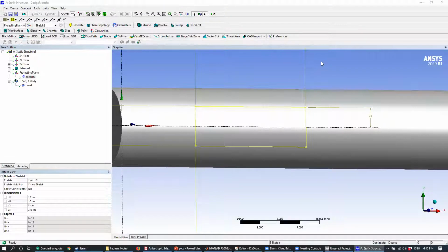You'd still have to sketch it, I think. So one way that I would do it is I would make a plane that's coincident with the feature that you want to project, and then make a sketch that outlines the feature that you want to project. And then once you have that sketch, you can follow the same steps as we followed just now. I don't know if there's an automatic tool for doing that, but you can definitely do it manually by drawing the sketch.